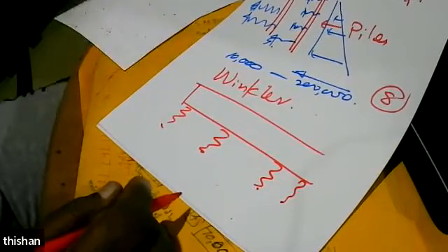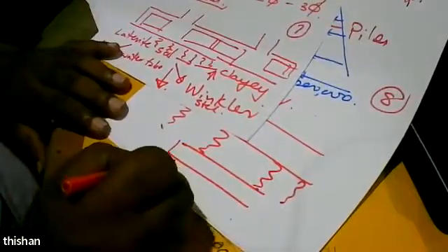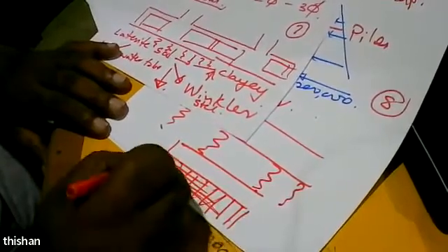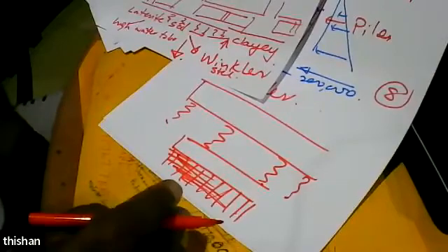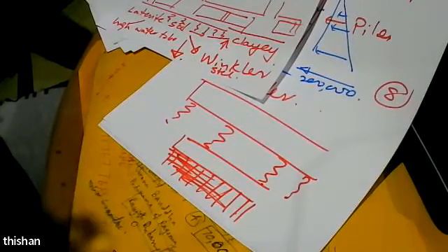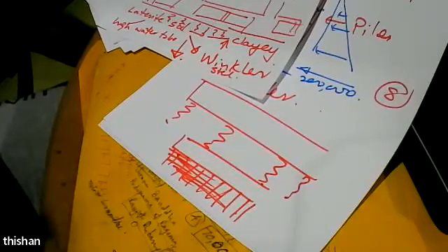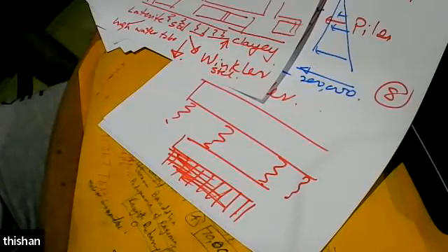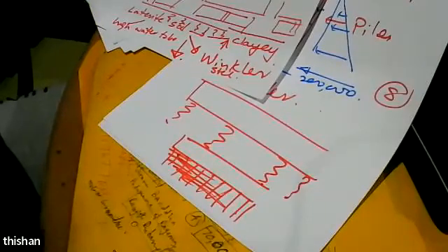But when it comes to clay soil, that is high water table with laterite, you have to model the soil. The last one is, so you use three-dimensional modeling, and instead of modeling the soil as springs or anything, you will actually go for the real representation of clay soil with an area which is much larger than the footprint of your building. Then only you can capture any effects of having softer material under the foundation.